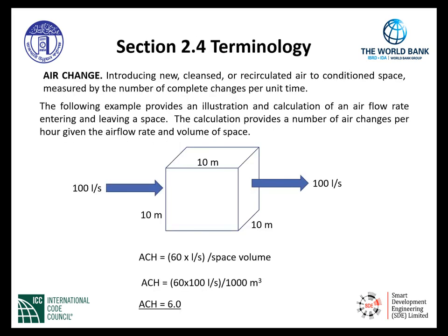Air change. Air change, by definition, is introducing new, cleansed, or recirculated air to conditioned space, measured by the number of complete air changes per unit time. The following example provides an illustration and calculation of an airflow rate entering and leaving a space. The calculation provides a number of air changes per hour, given the airflow rate and volume of space.